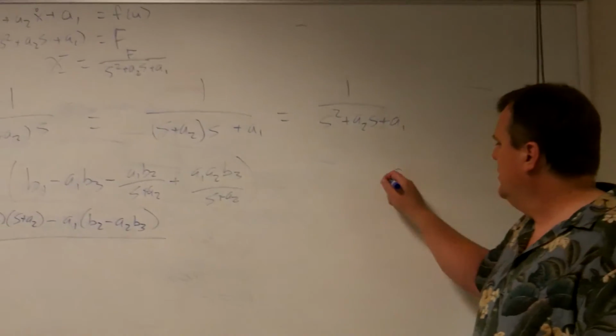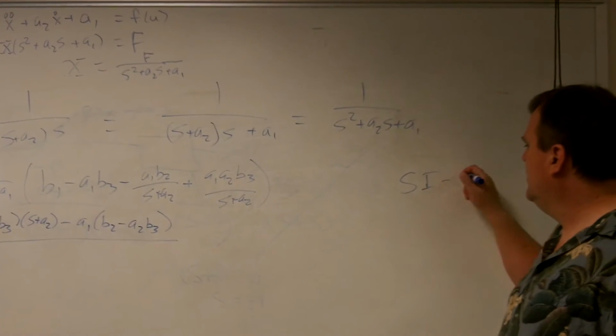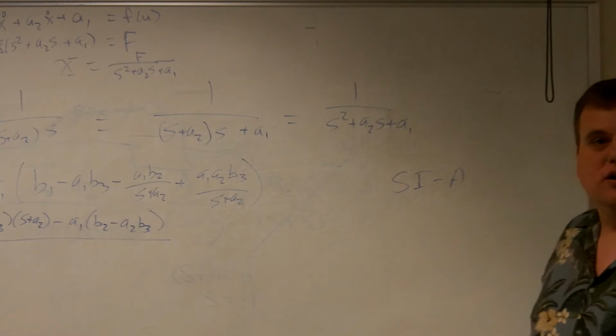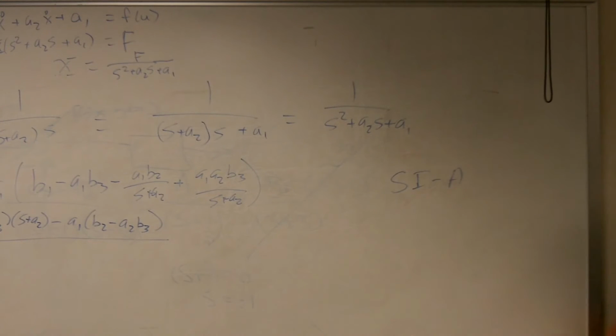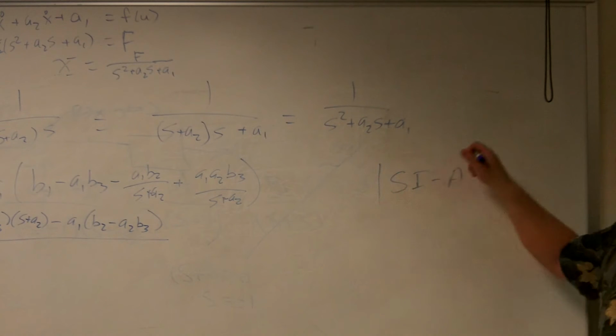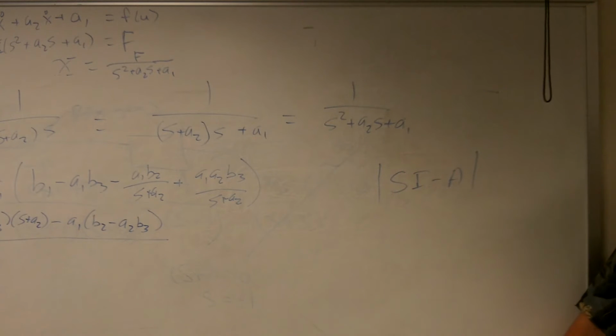So that means all the work you did before, once you found A, can just be written as sI minus A. If you find what the poles of that are, you found the whole thing. Well, that's where the poles are, where the system goes to 0 at those points. That's at the eigenvalues. Well, how do you find the eigenvalues? Well, you take the determinant of that. Fair?